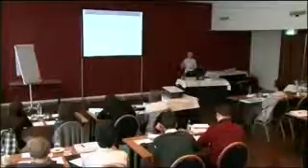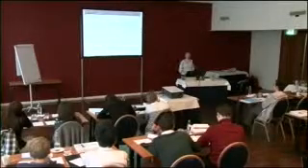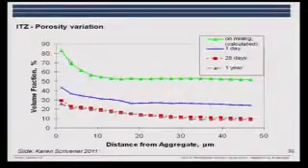Initially, when you make your mix and you have the larger aggregates, the cement grains cannot pack the same way just next to the aggregates. We have this wall effect. And then the hydration starts. This is what you see here on mixing, that you have a looser packing of the particles.